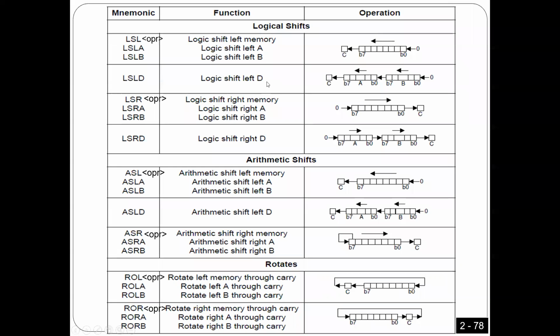So if you look here, this is how logic shift left is working. Let's look at how the arithmetic shift left is working. They are the same. That's what I told you last time. In case of shift left, arithmetic and logic are the same. What do I mean by the same? As you see here, I shift with 0, and the last one has to go to the carry. So in case of left, logic or arithmetic are the same.